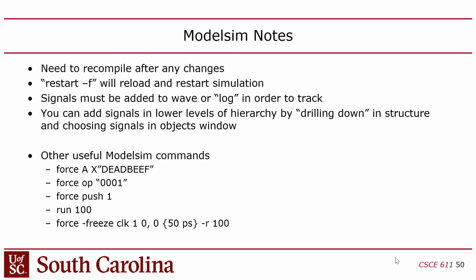So there's restart, which restarts the simulation. Whenever you change your design, you have to recompile it, right? And then you just restart. When you restart the simulation, it will reload the new design that you've compiled, right? You don't have to restart the simulator. A lot of people restart the simulator. You don't need to do that. Restart will restart you to time 0 and will reload the binaries.